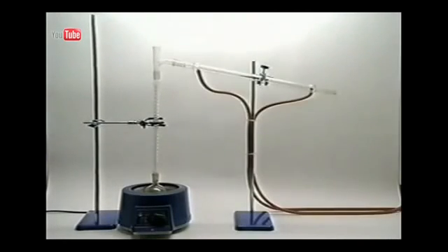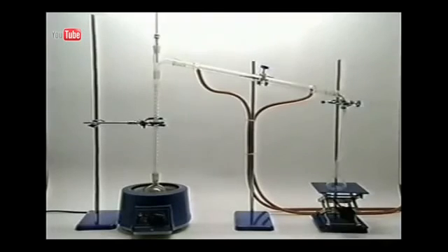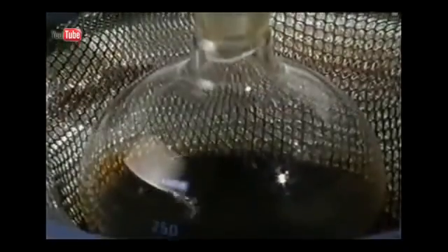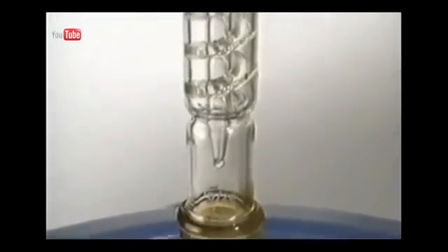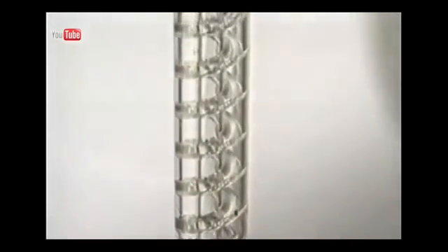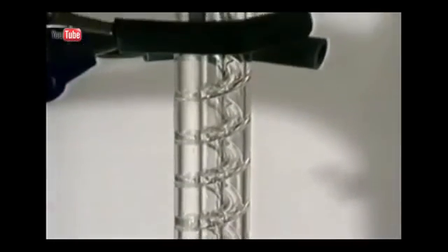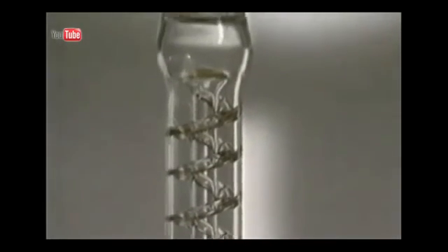The equipment is a combination of a still to warm the material and a long column above the still packed with beads. The beads may be glass, ceramic, or other non-reactive material. As the raw material to be fractionated is warmed in the still, the smaller molecules tend to evaporate first and move easily and higher up the column, followed by medium-sized molecules and then even larger molecules. As each material gets away from the warmth of the still, it starts to condense on the beads and dribbles back down to the point at which the warmth once again lifts it up, again and again.